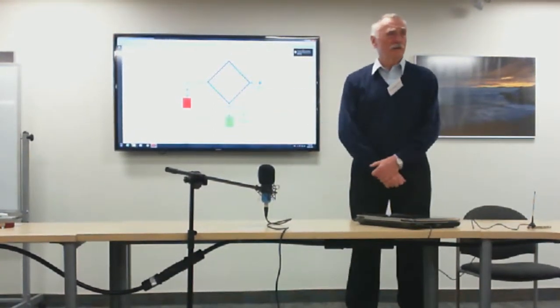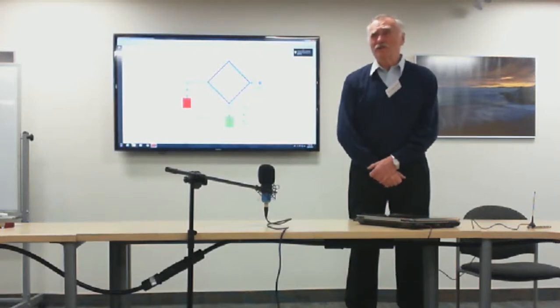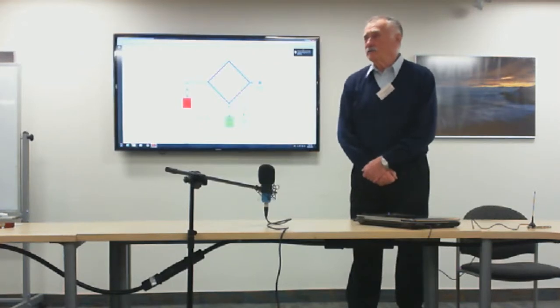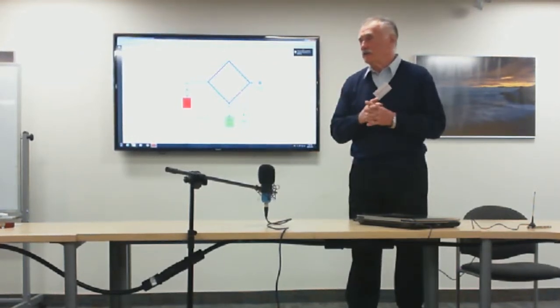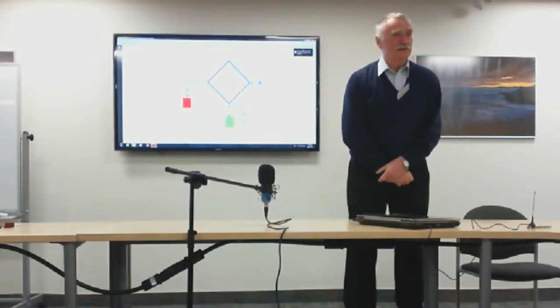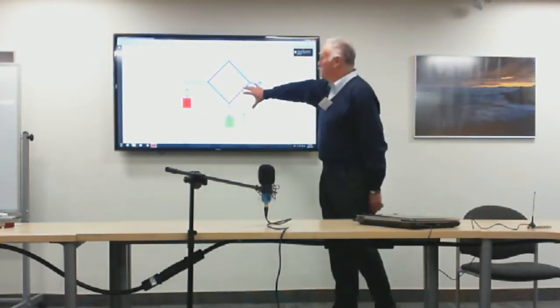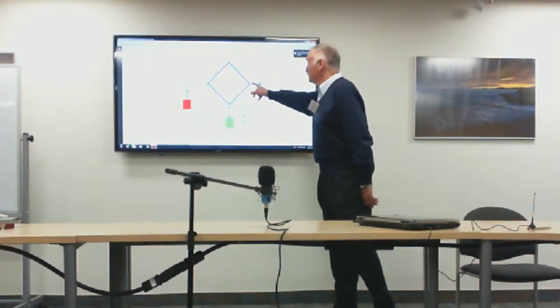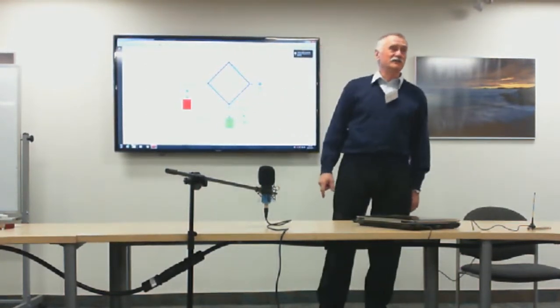Is there a problem with this setup? No problem whatsoever, just it's frequency dependent. So this is not used in a wide frequency range ham radio, but you have from 160 meters up to 70 centimeters. Maybe this setup could be used on 70 centimeters only, because how long should those coax sections be?